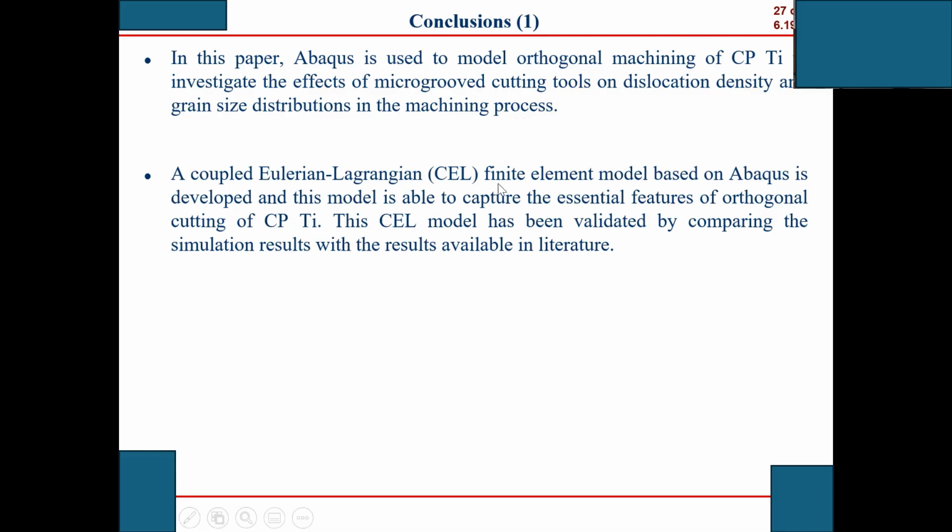So a coupled CEL FEM model based on Abaqus is developed, and this model is able to capture the essential features of orthogonal cutting of CP-Ti, and the CEL model has been validated by comparing the simulation results with the results available in literature. Because we did not do the experiments by ourselves, we use the experimental results that are available in literature as a reference for comparison.